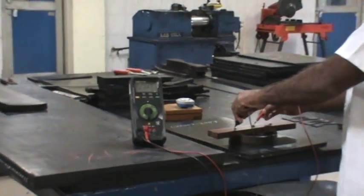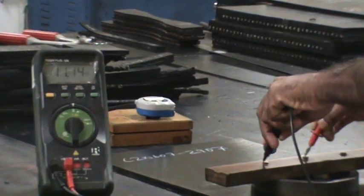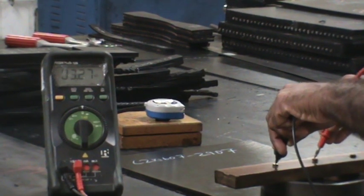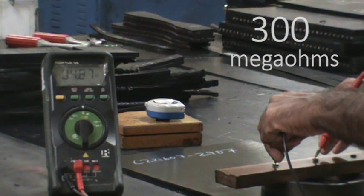High resistance means the rubber is a poor conductor and therefore can be used in electrical applications to insulate against electric shock. In the case of underground coal mining, the limits are set by Australian standard AS 4606, which states the belt must not have an electrical resistance greater than 300 megaohms.